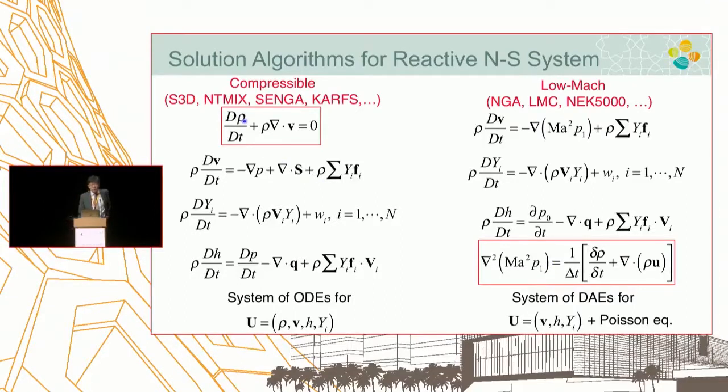Let me ask you one question. How can you assume incompressible flow when density changes from upstream to downstream of the flame by a factor of 7, 8? What is the definition of incompressible flow? Anyone? Okay, he gives you all the right answers. Very good. So don't be confused. In case you're wondering, it's a trick question. Incompressible flow doesn't mean constant density. That's a wrong answer.